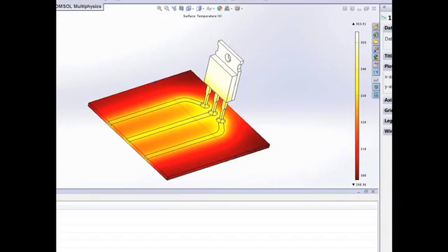Now, as a very last step, I would like to show how you would go about setting up a parametric sweep. And that is quite simple. As I mentioned before, all these steps of dealing with the physics, the solver and the post-processing are inside the same user interface. So all you have to do is find a node called Study in your COMSOL model, and then when you right-click on that, this node includes all the steps needed to set up a solution, to set up the solver. And the solver configuration is pretty much automatic. You don't really need to concern yourself with it unless you're doing more complex things.